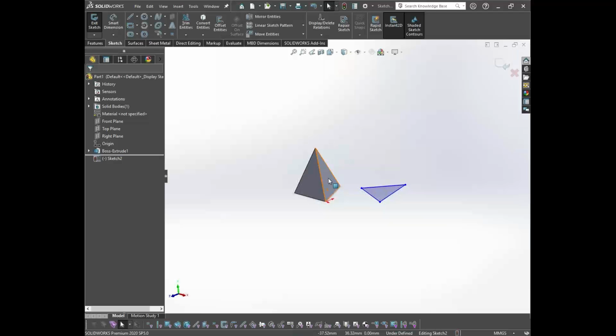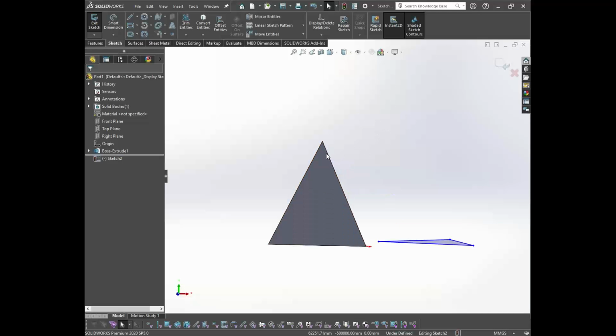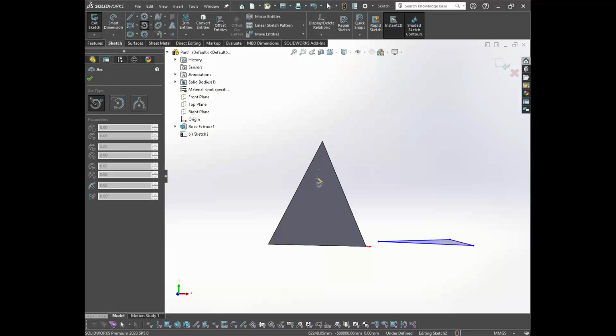In terms of solid elements, they have only 3 translational degrees of freedom, since the elements are quite stiff. If I apply a load on a single part of the element, it will move in the x, y, z direction. It won't be able to rotate. That is, if I'm fixing this and apply a load, we won't be able to see deformation. I'm showing you with the help of this.